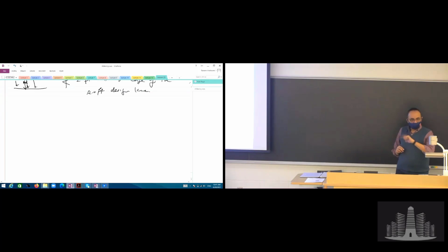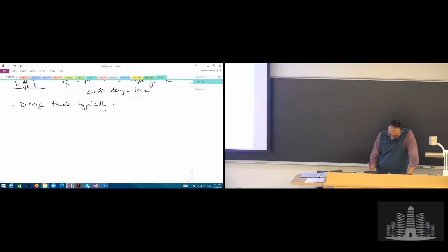As we have seen in the HL93, we have 2 options for trucks. We have the tandem, the 25 kip thing, and we have the HS20. Typically, HS20 governs here because of the heavier wheels in this case, but you may try both. So I just write down here that the design truck typically governs in deck design compared to the tandem vehicle.